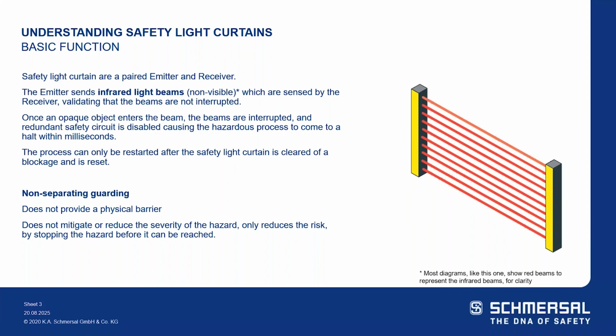So it's providing non-separating guarding. It does not provide a physical barrier, does not mitigate or reduce the severity of the hazard, and only reduces the risk by stopping the hazard before it can be reached.